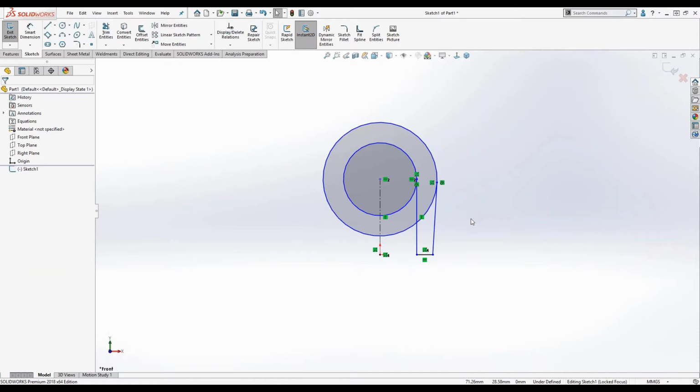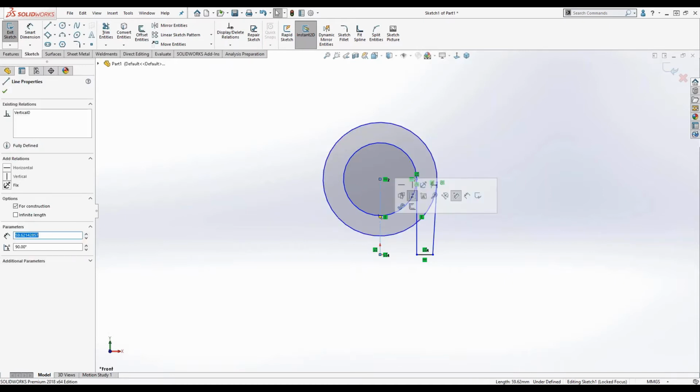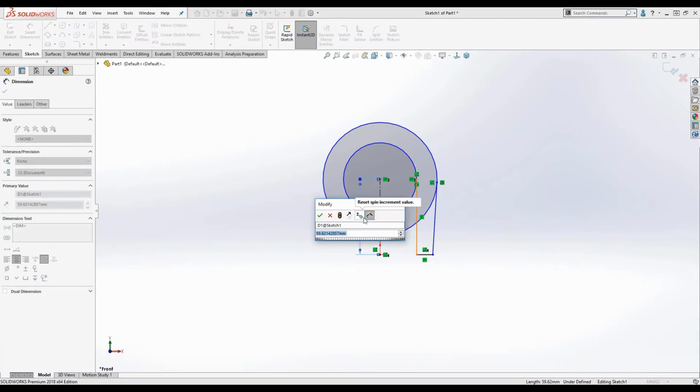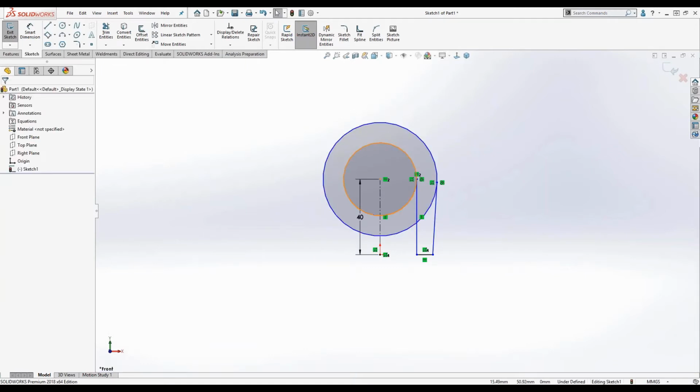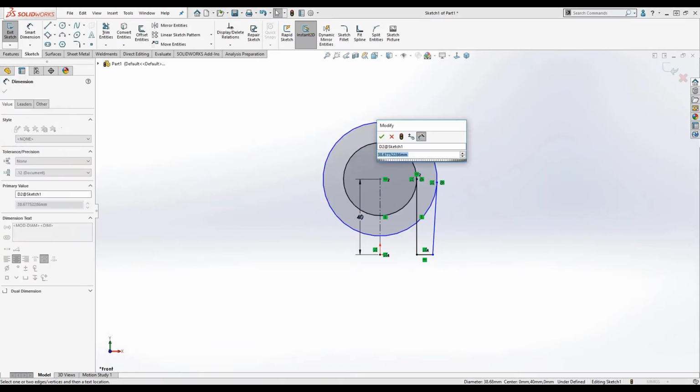And then one thing I really like in 2018 that they added is the auto dimension tool. So with that, all you have to do is click on a sketch feature, and there's this auto dimension insert here. So I'm going to start dimensioning my sketch because we know that we want to have this fully defined. So this is utilizing the breadcrumbs as well.